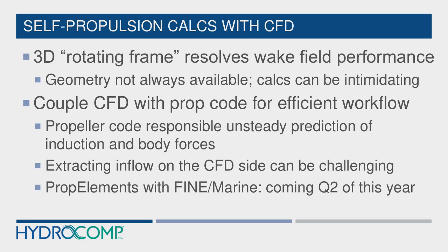Now, also, propeller calculations, full rotating frame propeller calculations, can be a little intimidating, and there's still some skill needed in determining, how much do you rotate the blades for each time step? What kind of grid refinement do I need? What's appropriate in order to model the different kind of characteristics?